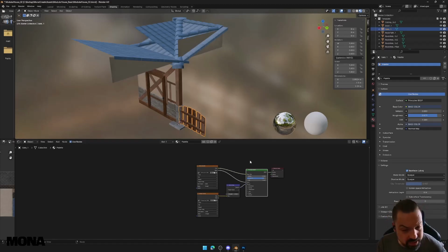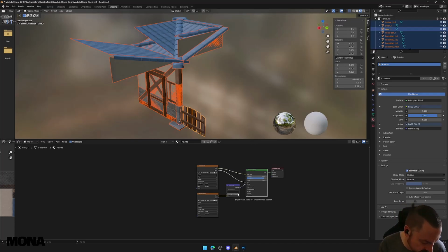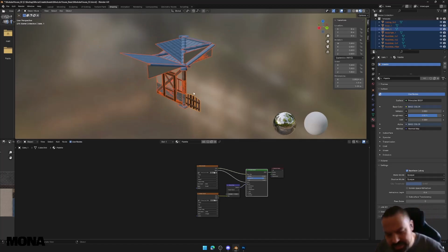Sometimes, like if you apply a material, so if I selected all these objects and applied a material, pretty much all the time, it doesn't apply to all of them. It's one by one. So I think you have to use copy material and paste to selected. Oh, there we go. Copy material to selected. So that's a quick way to do it. But in my mind, select them all, apply them, done. Okay. So that's materials, done.